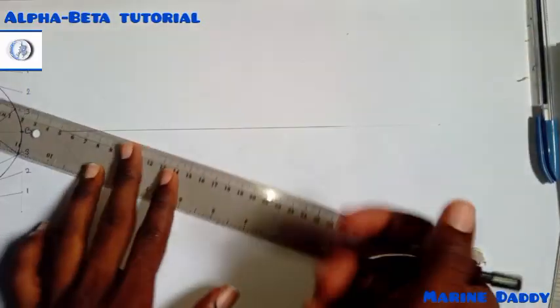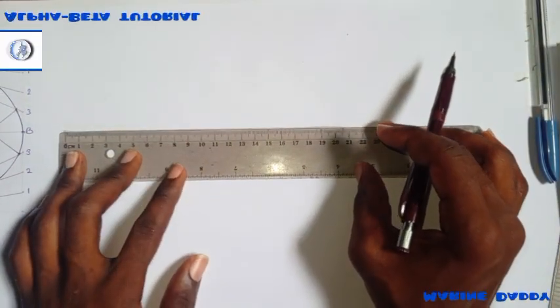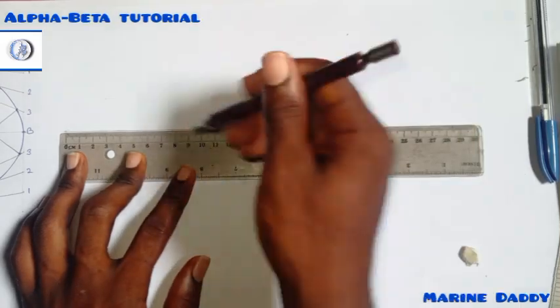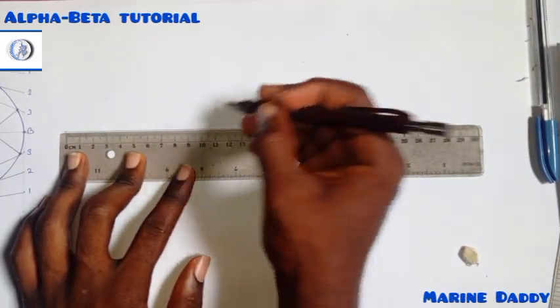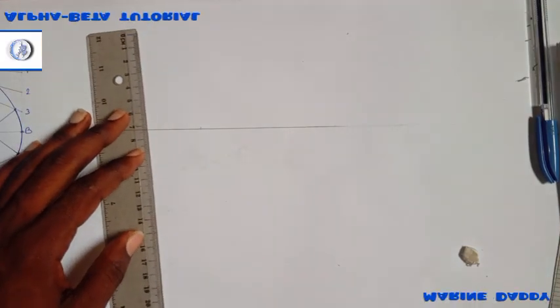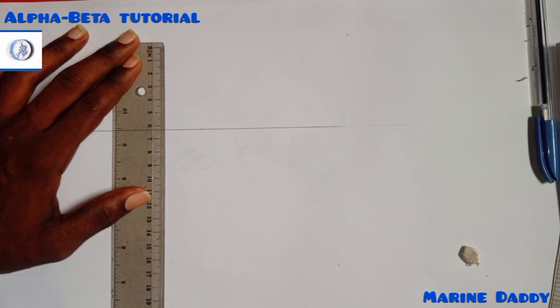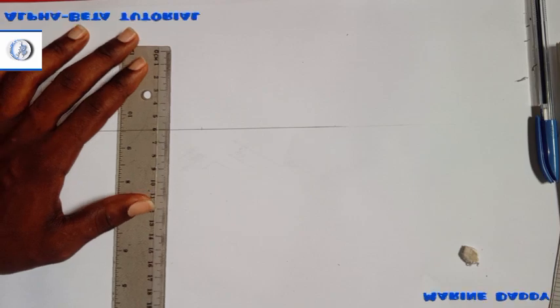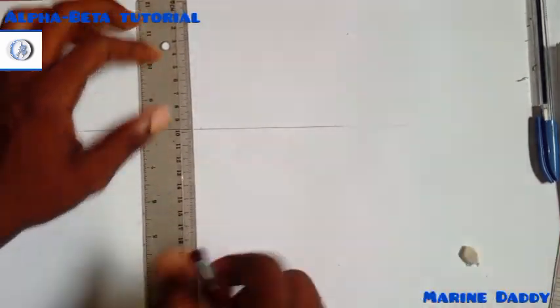So from that middle, you are going to draw a perpendicular line. From that middle, you draw a perpendicular line and draw your minor axis, which is 12. So the minor axis will also be balanced at the middle. Which simply means that 6 will be at the top, 6 will be at the bottom, perpendicularly. So this is what you are doing.